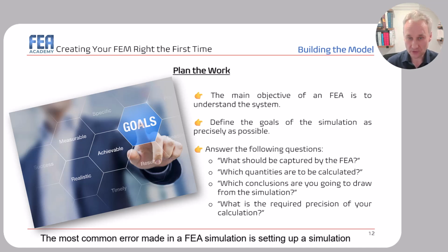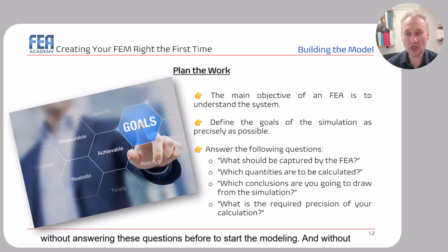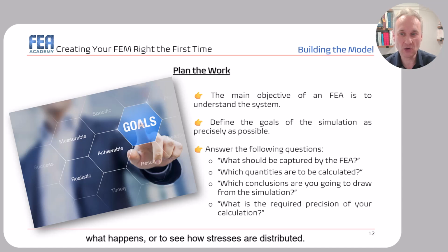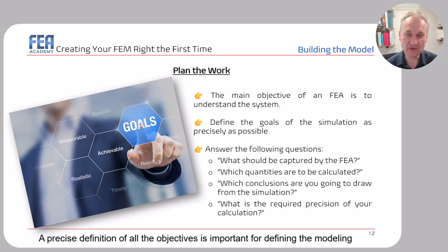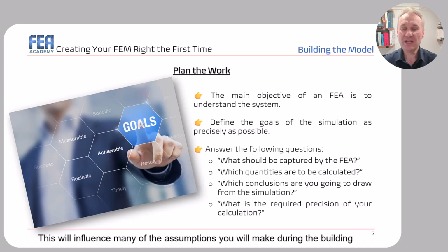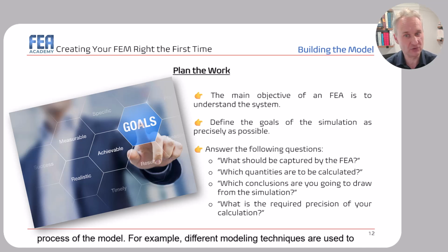The most common error made in FEA simulations is setting up a simulation without answering these questions before starting the modeling and without having a clear goal in mind. So I recommend you never set up a model just to see what happens or to see how stresses are distributed. A precise definition of all the objectives is important for defining the modeling techniques and the solution you will use. This will influence many of the assumptions you will make during the building process of your model.